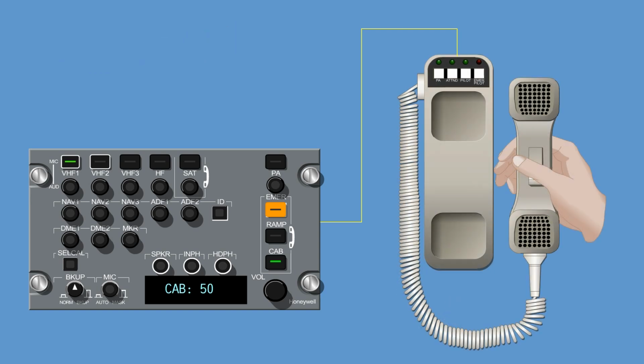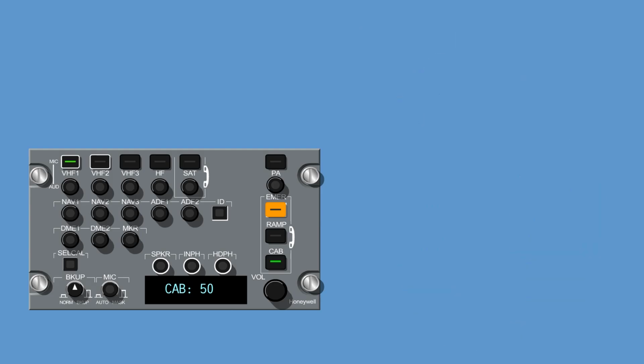When established, the display shows the characters cabin plus a number between 0 and 100, denoting the volume. If the pilot selects another microphone push button, the cabin select push button remains lit. To return to this cabin, the push button must be pushed again.